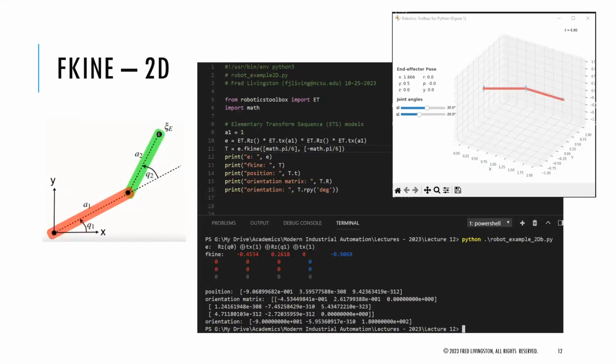And I showed some Python code to do these, and this is what you're going to be using to assist with your last homework. Given the robot system, you need to compute that A matrix or that T matrix in this case here, and then you need to extract the location of your part and the orientation of that part. And you can utilize these scripts to help you write the code here. You have to add some more stuff to your code to make it for the correct robot.